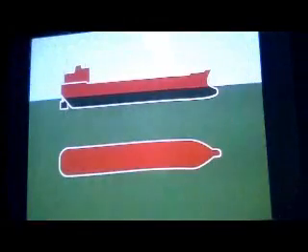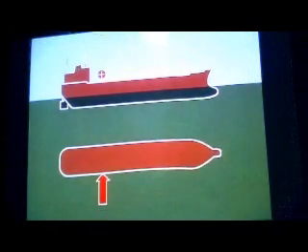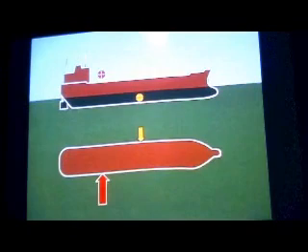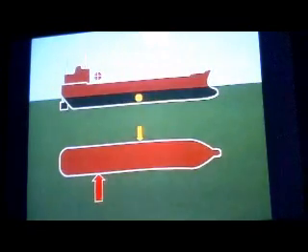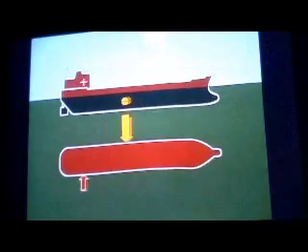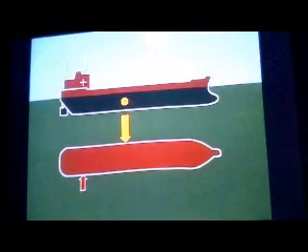A change of draft will also cause the aerodynamic and hydrodynamic centers of pressure to change their positions. Change of aerodynamic center of pressure is particularly evident with all-aft ships. The aerodynamic force will decrease as the hydrodynamic resistance increases. The couple resulting from these changes will produce a new equilibrium position and drift speed.